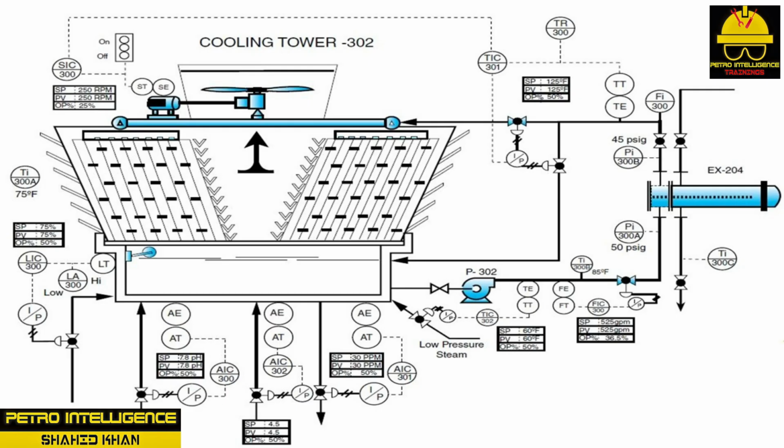16. Record T300A wet bulb temperature, WBT. 17. Record T300B. 18. Calculate the approach to the tower. 19. Carefully monitor all conditions and collect makeup water sample, basin samples, and P302 discharge. 20. Verify all process variables with standard operating procedure.